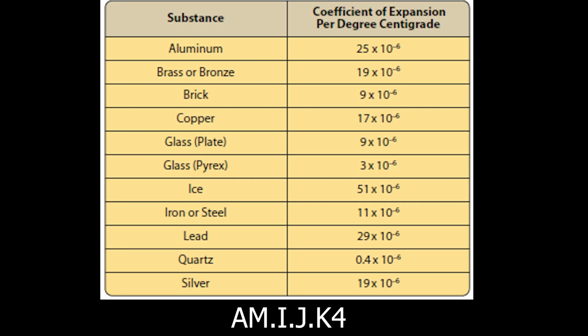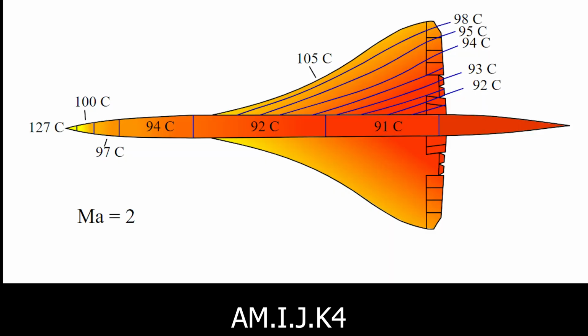Thermal expansion and contraction occur in solids, liquids, and gases when heated. Solids generally expand when heated and contract when cooled, although to a lesser extent than liquids and gases due to their closer molecule arrangement and stronger intermolecular forces. Although the increase in length due to thermal expansion is relatively small, it can exert tremendous force if the object is constrained from expanding freely. This phenomenon must be considered when designing aircraft structures, engines, and related equipment.